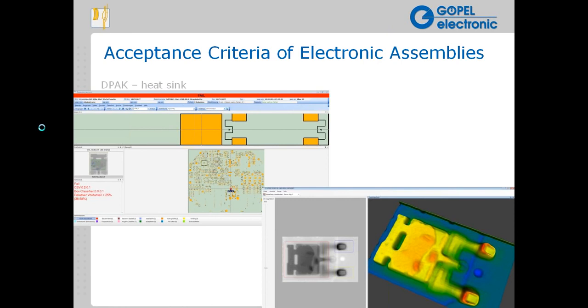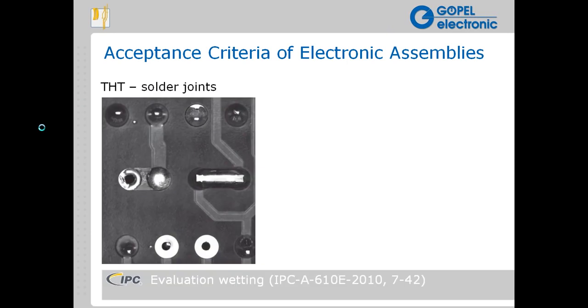Looking at this a little bit more closely, a through-hole solder joint does not only consist of solder contacts on the surface, it also consists of the barrel fill, or the solder fill of the hole itself. That is something that is not inspectable at all with AOI. Electrical tests can reveal problems there, but often do not. Barrel fill issues are probably more of a lifetime or dependability problem, and not usually detectable immediately through electrical tests. So this is an application where X-ray can become very important for inspecting high dependability through-hole joints.